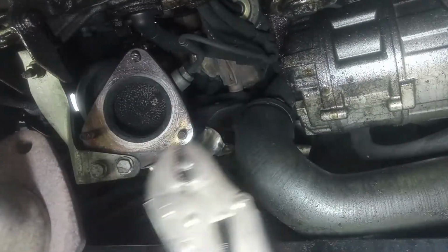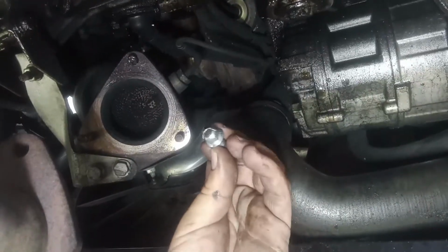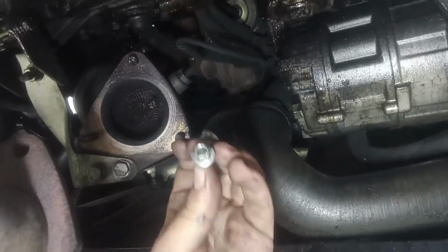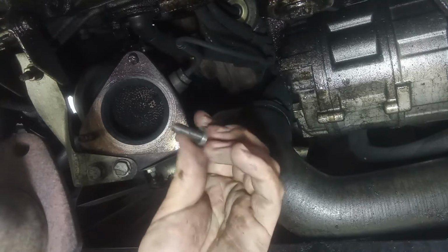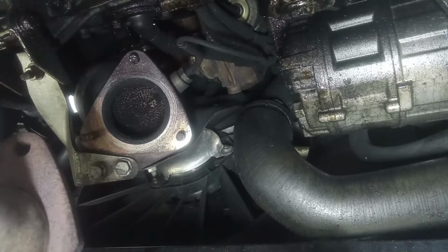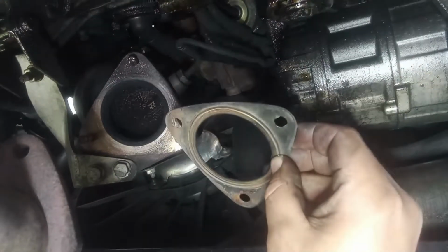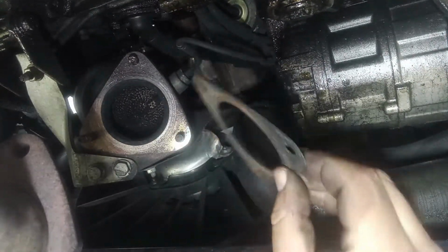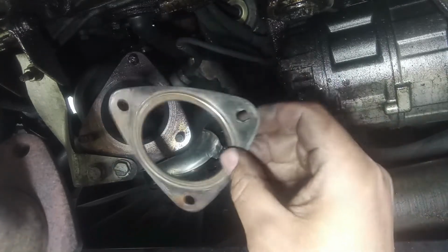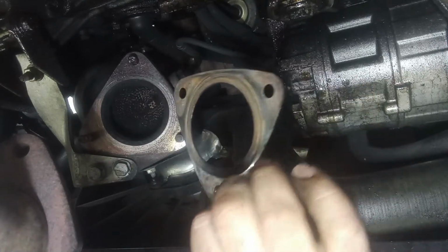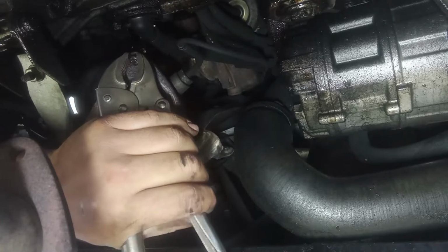tightening. Well, I hope to be able to take that out, and then I have a new stud and a new 11 millimeter nut to put in there. I just had that in stock here in house, but you can find this at the dealership, no issues. Very easy to find. So try to remove that. Again, the gasket is a metallic one. You do not need to put any paste, any exhaust paste. Nothing, it just goes in dry, okay? And you can reuse it a bunch of times. So try to get a good grip.